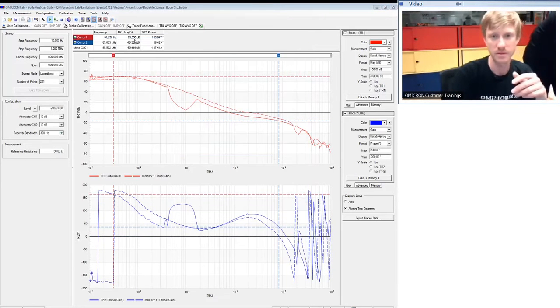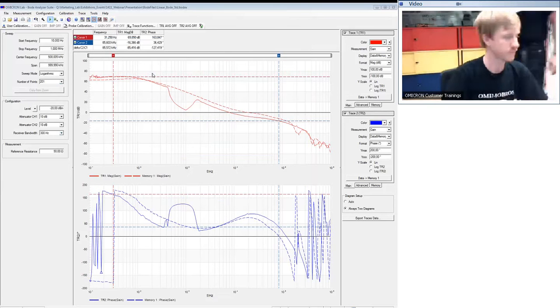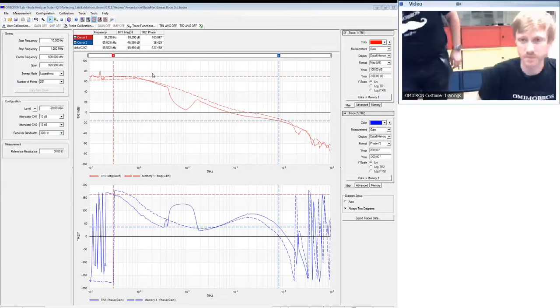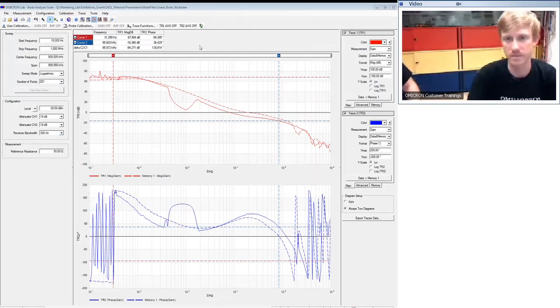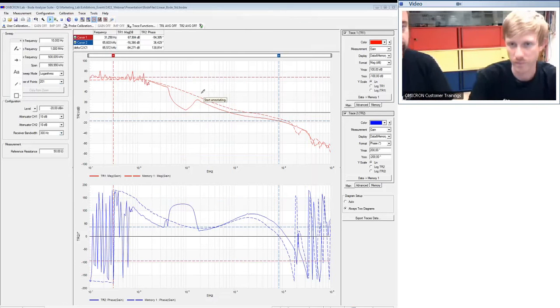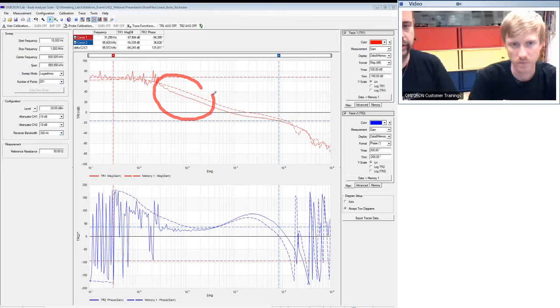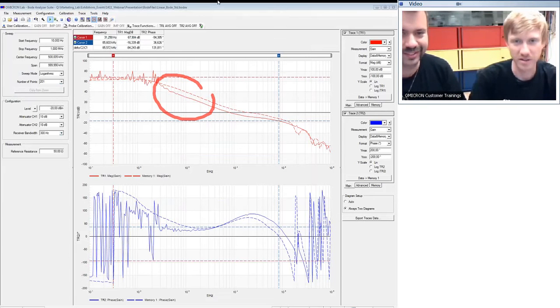And as you can see already, we have a level problem. So the level is too high for this measurement. We have changed the output current. We reduced the output current. Okay. Now it's gone. The effect is gone. Okay. It was the high level from before.